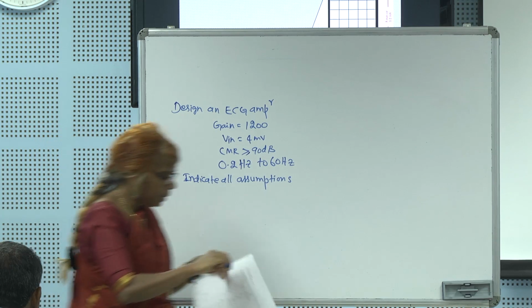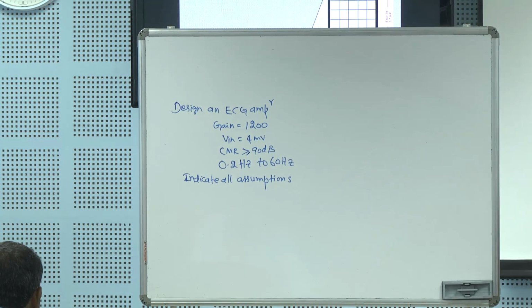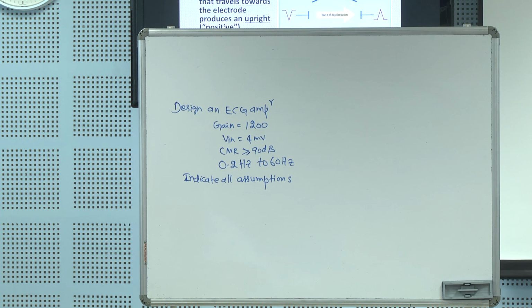I will open that, follow the initial stage, the same thing. The pre-amplifier, everything. Use the 22 kilo ohm, 10 kilo ohm, keep that 5.4 and then the 4.7, all that, and then only change the second stage. Here.